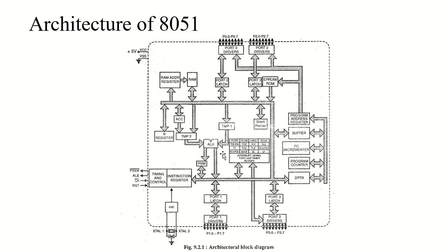So for addresses higher than 0FFFH, the 8051 will automatically fetch the program code byte from an external memory, by connecting the EA pin to ground.